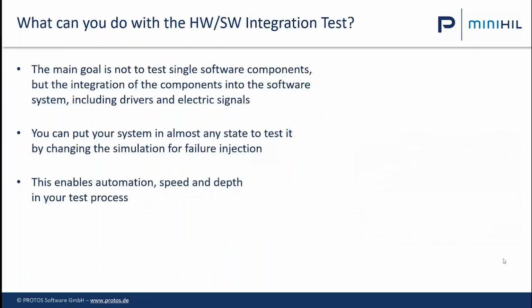Now, what can you do with such a hardware-software integration test? The main goal is not to test a single software component, for example, a motor controller or a battery controller or a bus protocol or something like that. You can test this, but you want to test the integration of the components into the complete software system, including all the drivers and electric signals.